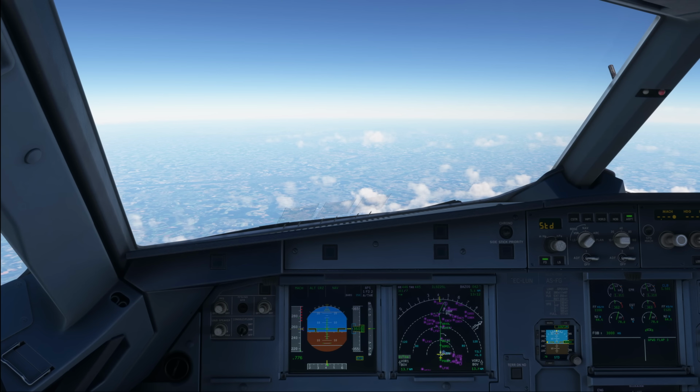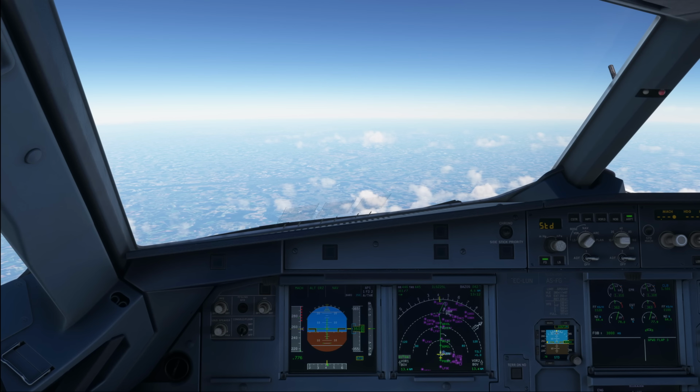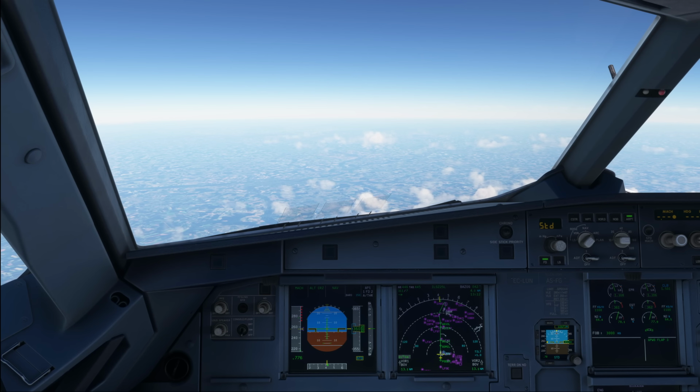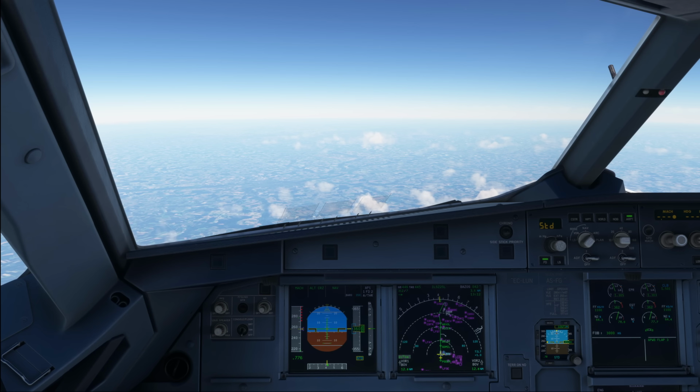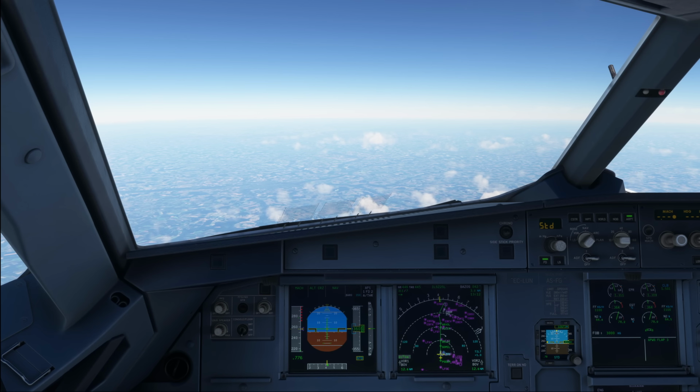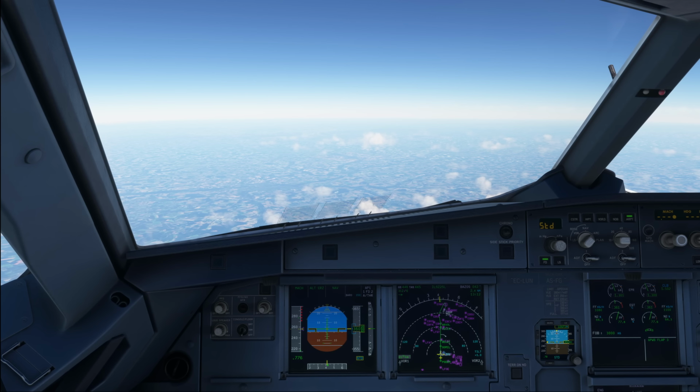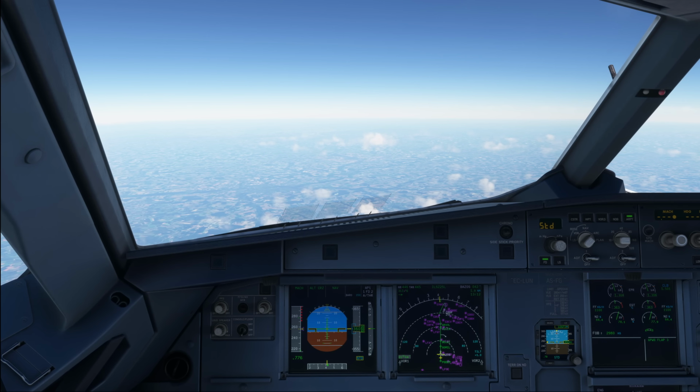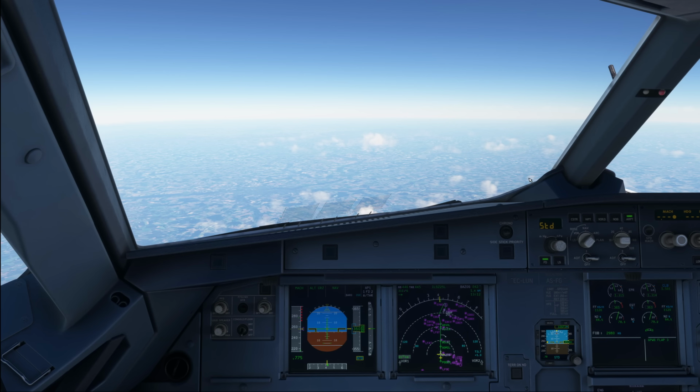After landing then, the flight crew should delay for as long as possible the start of the APU, and if only the ground pneumatic unit is available at the gate, the flight crew may keep the APU bleed off during transit. One engine taxi again is recommended, and I do refer to my separate video on single engine taxi for that. Now, if one pack is sufficient to supply air when on the ground, the flight crew can select one pack to off. In such a case, the flight crew should switch between the packs on each flight in order to prevent excessive wear of one pack.